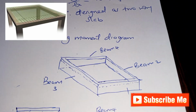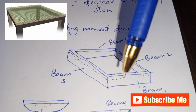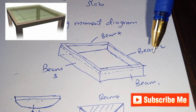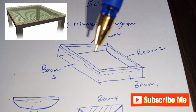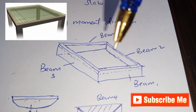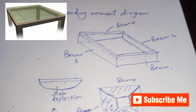For a two-way spanning slab, the suspended slab is being supported on four sides. In our illustration here, we have beam 1, beam 2, beam 3, beam 4, and in between we have the suspended slab. So this suspended slab is being supported by four directions, or rather four beams. That is a two-way spanning slab.